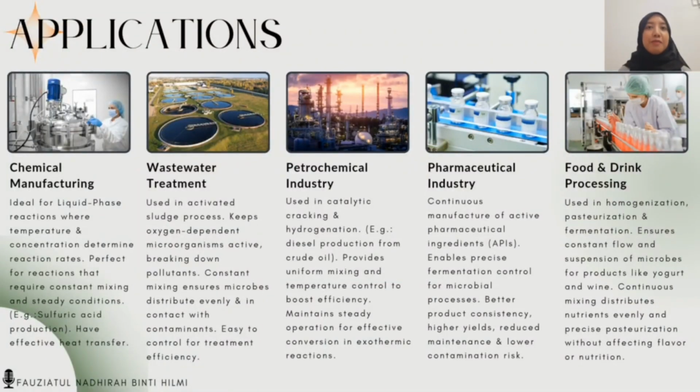The next part, the application of CSTR. The first one is chemical manufacturing. It is ideal for liquid phase reactions where temperature and concentration are important to determine reaction rate. It is also perfect for reactions that require constant mixing and steady conditions such as sulfuric acid production, because of its effective heat transfer.